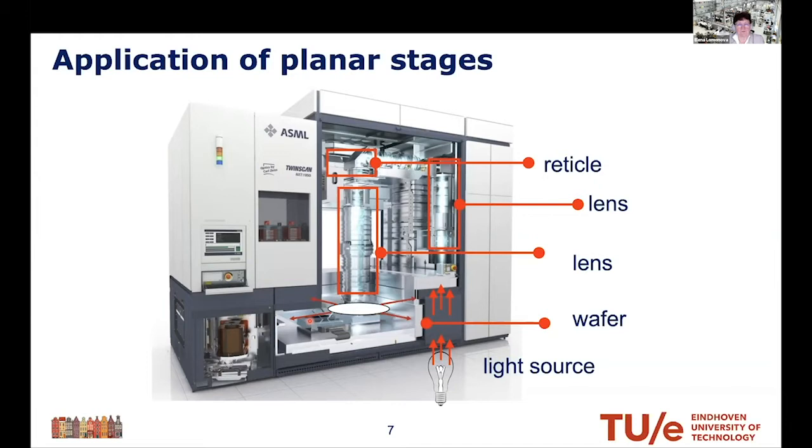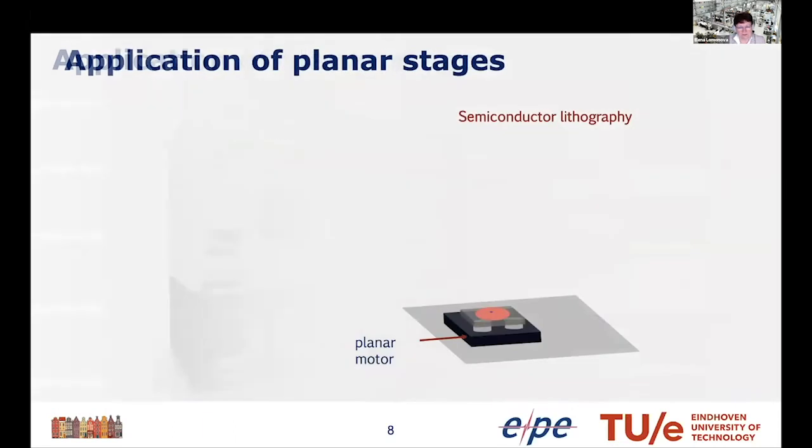So the movement of the wafer will be in the planar stage. And as I mentioned before, it has to be freely supported, and the platform itself, which is supporting the wafer, has to be able to levitate. If we're looking at the planar motor, which is introduced by the black color here schematically, we have a wafer on top of that, and this is a long stroke electromagnetic planar actuator, so a combination of permanent magnets and coils only. Any inclusion of ferromagnetic materials should be excluded because ferromagnetic material is the subject of forces between the moving body and the stationary body. So we have to avoid by all means the attraction force, which is rather intensive or high.